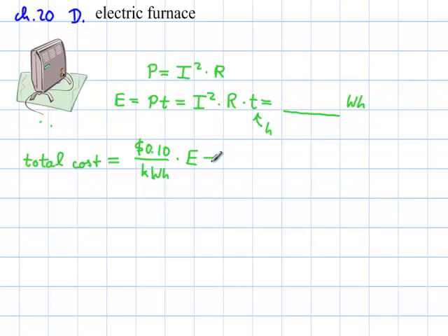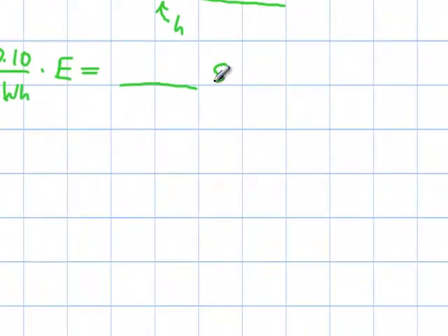And so I plug that in. Basically, you come up here at watt hours converted, shift the decimal point 3 times because of the kilo, multiply by $0.1, and you're going to come up with the total cost. And that would be in dollars. And on your energy bill, that's actually what you see is how many kilowatt hours you have been using. The result should be in the neighborhood of about $100 when you're done with it.